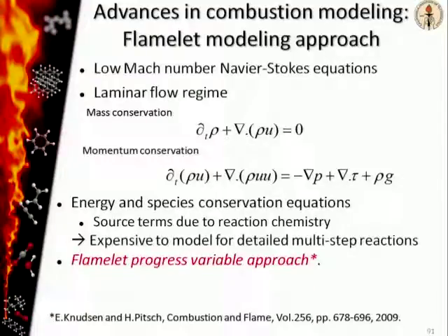So one of the things that we do is that we try to simplify the problem, first of all, as much as possible. So if we consider a reacting flow problem, where you have fluid dynamics coupled to some sort of chemistry, let's first of all throw any turbulence out of the problem and just focus on a laminar flow regime. You also make an assumption that you're operating in a low Mach number space, which means that you're pretty much incompressible. And so this allows you to solve a set of simplified equations. In this particular regime, you would have an expression for mass conservation which looks something like this, and momentum conservation which looks something like this.